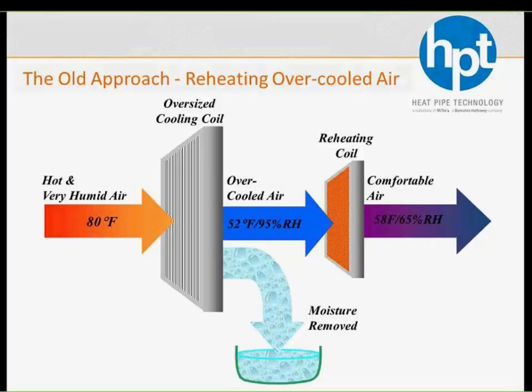So this process is extremely not energy efficient, and your costs are on both sides of your cooling process, not only by oversizing your cooling coil, but also the money you spend to heat up that air to get it to a nice 65% RH.